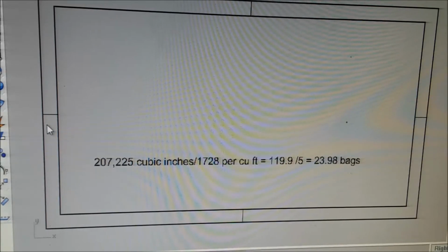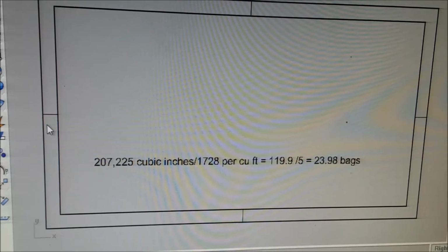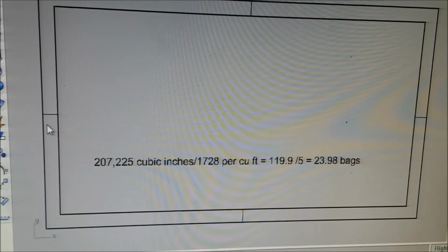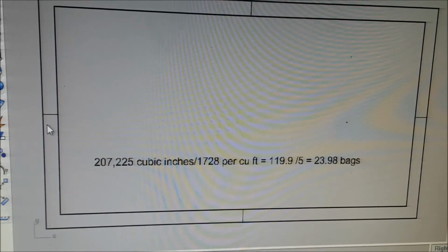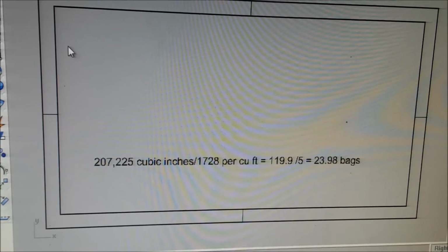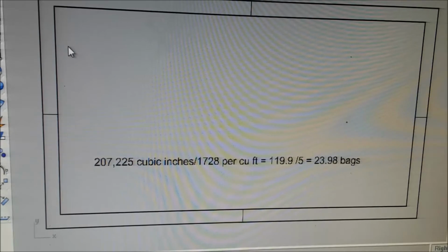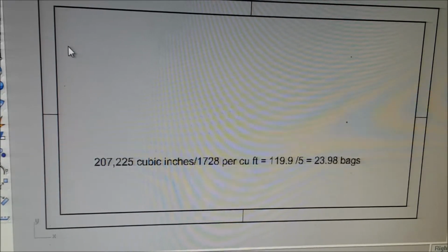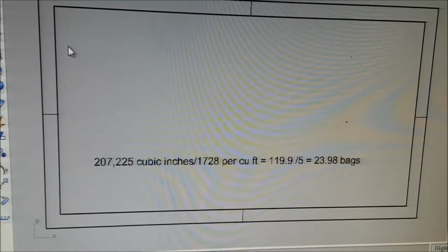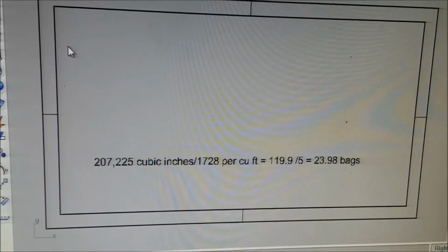Because we're using a computer on this, we can get our length times width times thickness with a single click. But in the normal run of things, you need to know how long your pour is, and how tall you're going to pour, and how thick the wall is. It's just simple volume. It's just not shaped like a cube or something. It's the shape of your house.